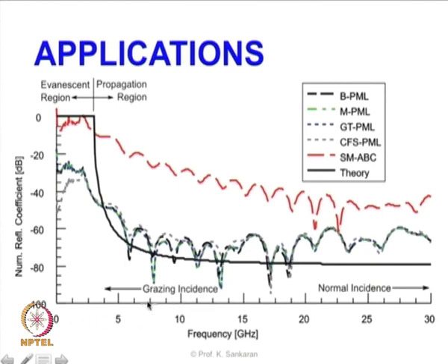So when the frequency is becoming less and less, irrespective of the fact that there are going to be more cells per wavelength, we see a poor performance of the PML and also the Silver-Müller boundary condition. So we see that as we increase lambda or decrease the frequency, the performance is deteriorating, and this is the importance and also the uniqueness of this particular graph.